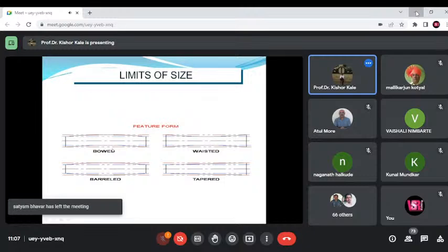These are 1, 2, 3, 4, 5. You might have seen when GD&T is being shown, they say GD&T is 14.5, indicating there are 14 types. Actually, the characteristics are 14 and 5 types of tolerances are there: form tolerance, profile tolerance, orientation tolerance, location tolerance, and runout tolerance.